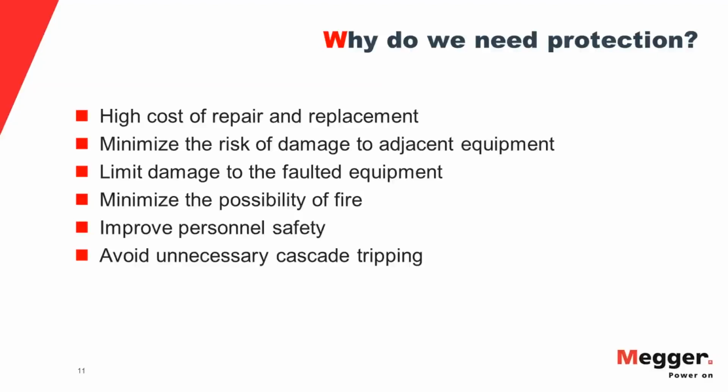We also can minimize the risk of damage to adjacent equipment if we design an effective protection scheme. We can also limit the damage to the faulted equipment if we take out the transformer as soon as we can.